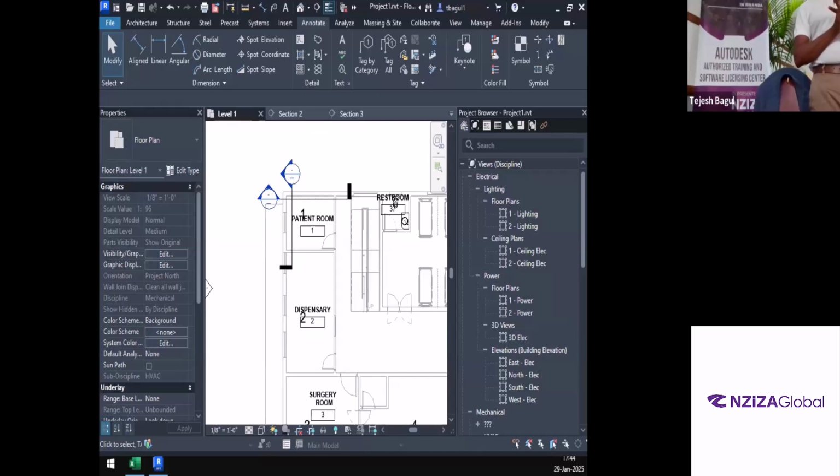All right. The equipment. Let's say you're working on an MRI room, that equipment is huge, right? The CT scan is huge. The amount of heat dissipated from that equipment might be even more, in the tune of 30 to 40 kilowatt. I've seen that equipment going 30 to 40 kilowatt. So that is a big room, and a big AC unit might be required.